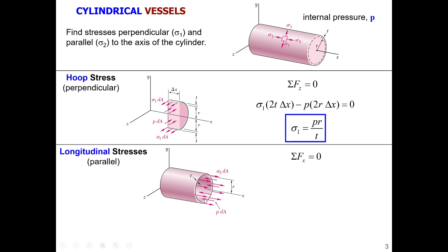So we still have stresses acting through the thickness here and pulling this back. The rest of this cylinder pulls the part that is on the left back here, and this is equilibrated by the forces that the fluid inside pushes in this direction, right? So it pushes essentially here, okay? And so we need to calculate the whole area, multiply our stresses by that area, and that will be the force that corresponds to the elastic stresses that develop in the structure.